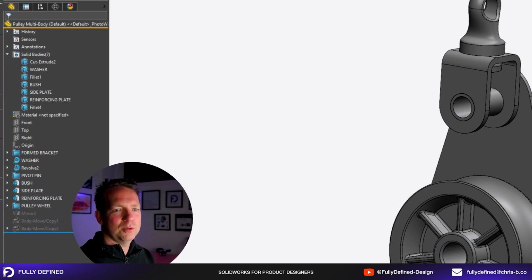All I want to do here is just for these last couple, because when I'm exporting, I don't want to export duplicates of those bodies. I want to make the duplicates from one part file in the assembly, so it's easier to manage, okay? And if I had to make changes, or I was changing some features of those parts, I'm not changing it for multiple files, I'm just changing it for one. All right. So I'm going to suppress those to start.